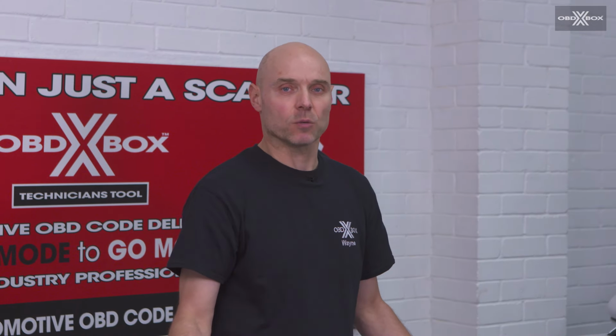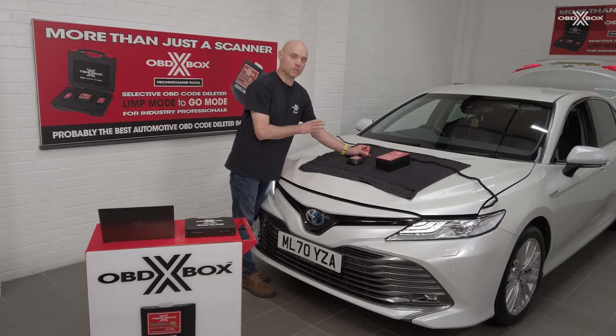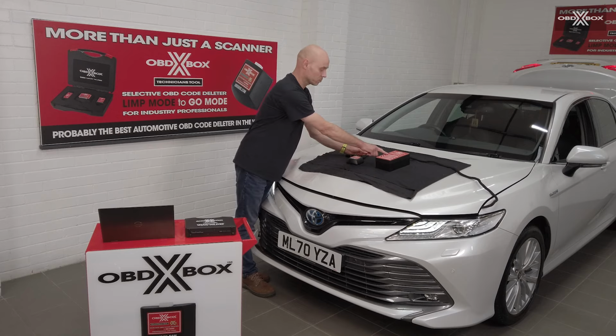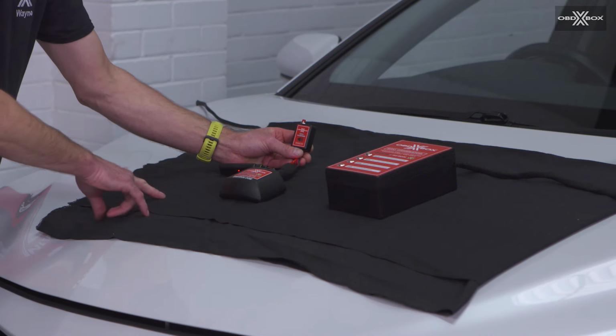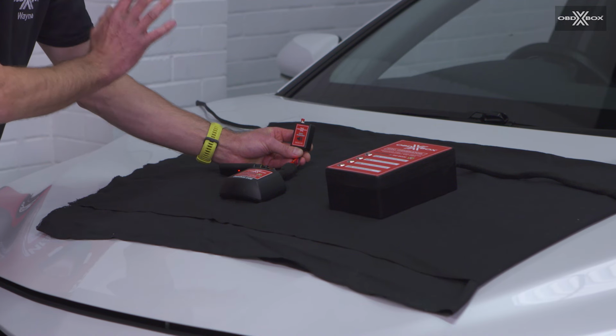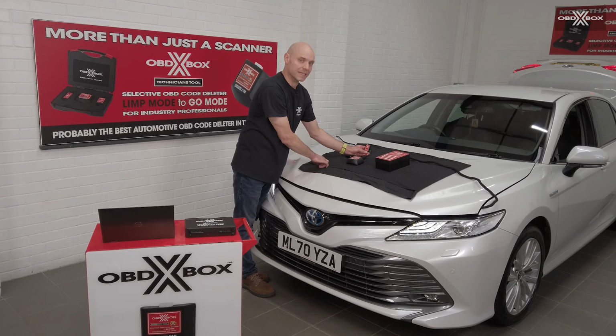The laptop has already been set up to deal with the code I'm going to introduce. You'll hear a short beep from the DTC alerter speaker when the fault's introduced. You'll hear a long beep when the code is cleared. There's the short beep, the fault is registered. There's a long beep for the fault being cleared. It was followed by a short beep because the fault still exists. Fix the fault. There's the long beep of it being deleted. No more beeps, the fault is cured.